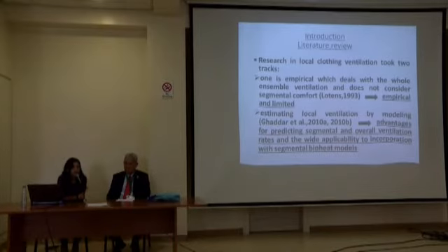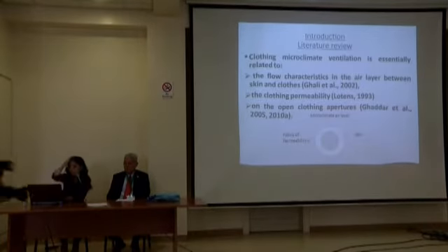One was empirical, which deals with the whole ensemble ventilation and does not consider segmental ventilation. And the other is by modeling, which has advantages in studying the effect of permeability, garment apertures, and wind conditions for predicting segmental and overall ventilation rates, and the wide applicability to incorporate with a bioheat model that did use the core and skin temperature.